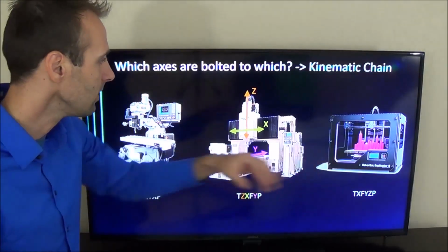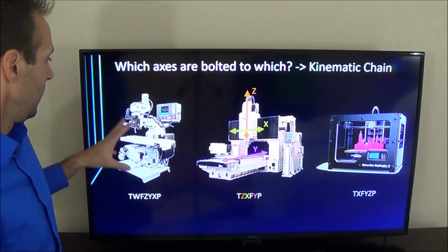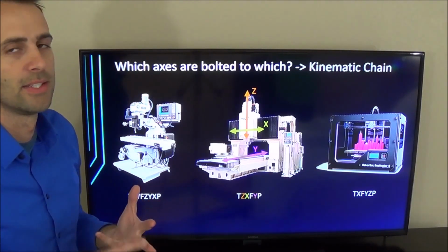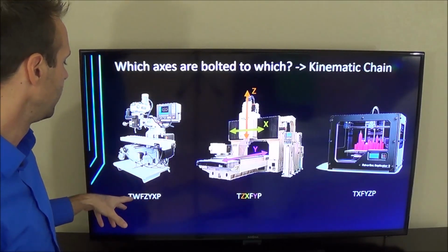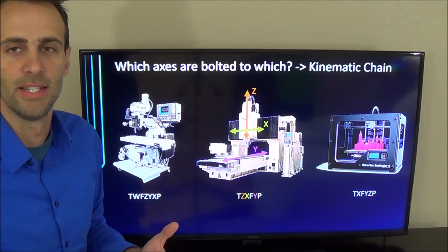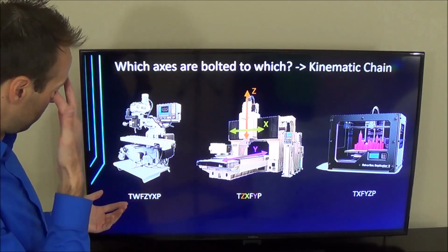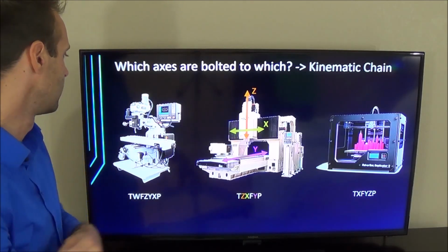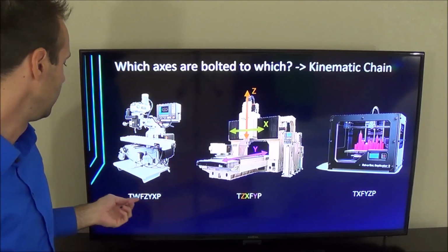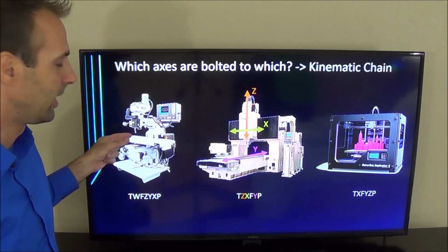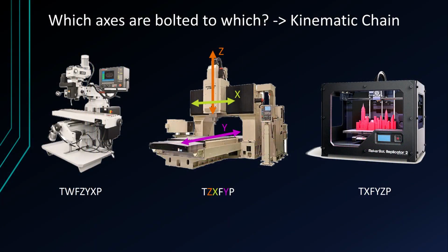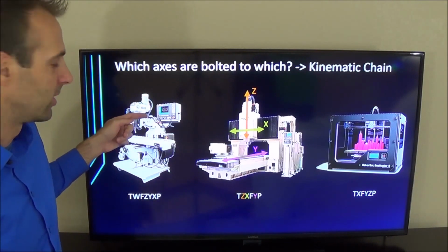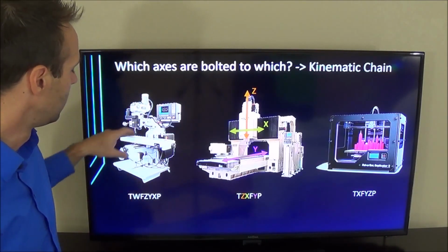When you get into redundant axes, rotary axes, things like that, you have to define some other name, X, Y, Z, ABC. Typically on larger milling machines, this redundant Z-axis would be called W. So for example, on this knee mill, the tool is in the W axis, which would be the quill, which is in the frame.